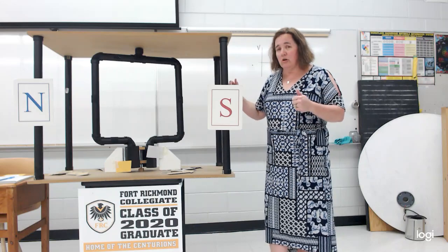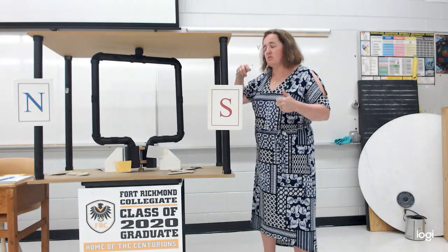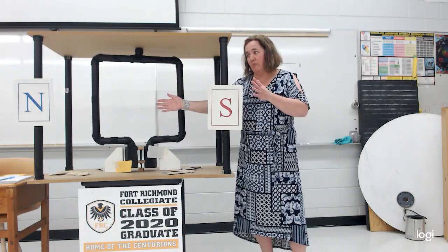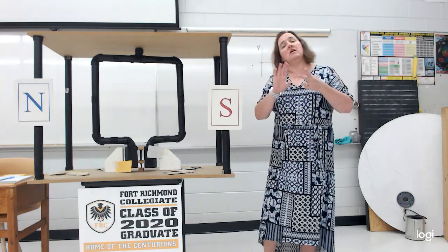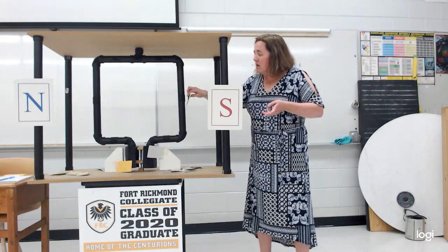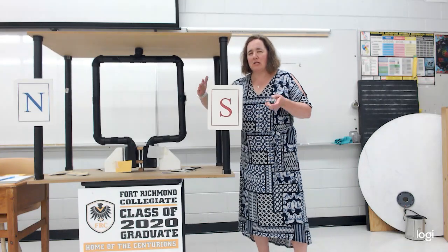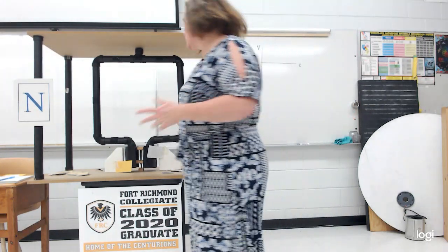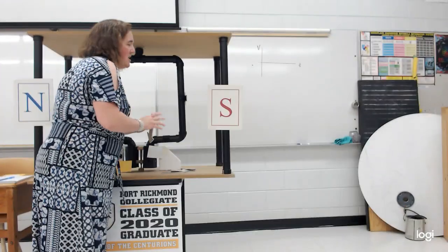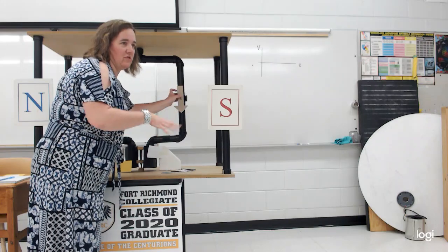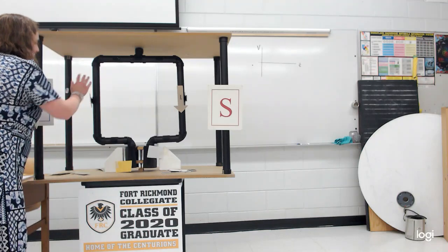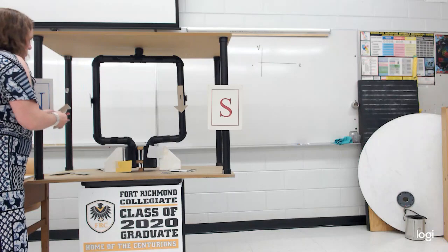Okay, so how is this different? It's still a generator if I rotate using wind or water or something like that. I rotate this armature in the external magnetic field. So mechanical energy goes in, electrical energy is going to come out. So I'm going to use my velocity vector arrows into the page. Hopefully this feels a little bit like deja vu. So we have velocity into the page, fingers going that way, palm faces down, which is technically EMF, but we're going to just say current for now just to keep things moving. Here, same idea, velocity is coming out of the page, fingers go from north to south, coming up that way.